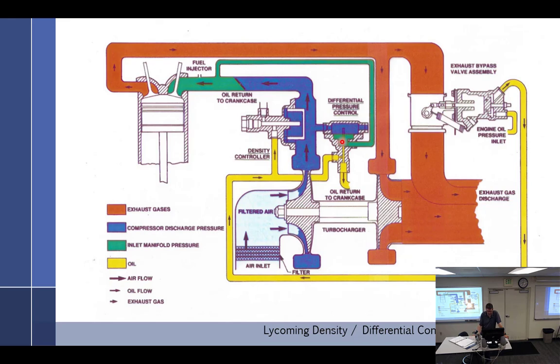This allows differential controller to adjust the wastegate. So now the wastegate's going to open a little bit. Let exhaust gas go that way. And that helps to prevent what's called bootstrapping, from pick yourself up by your bootstraps, which is very difficult. You just kind of reach down and grab it by your boots and try and lift yourself up, and it doesn't work so well. But I'll write down what bootstrapping is in a minute. It's basically where it's sort of a runaway. It's very sensitive and runaway.